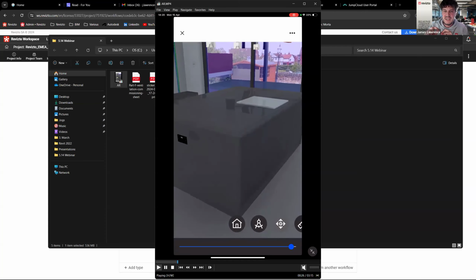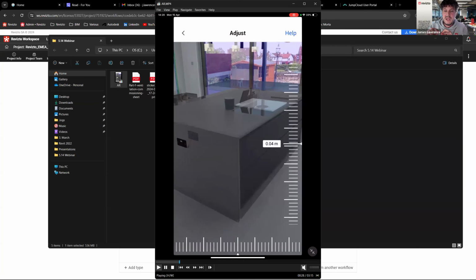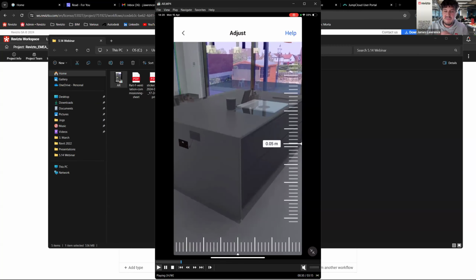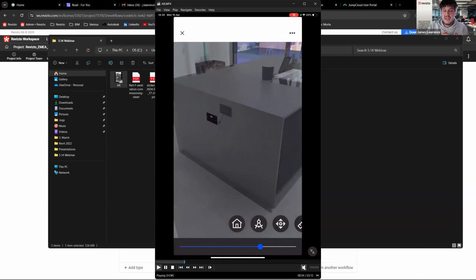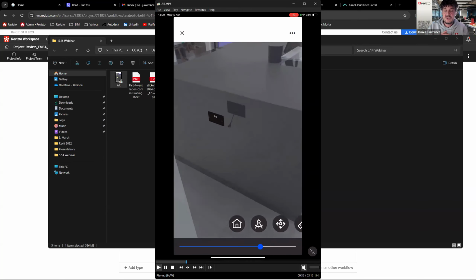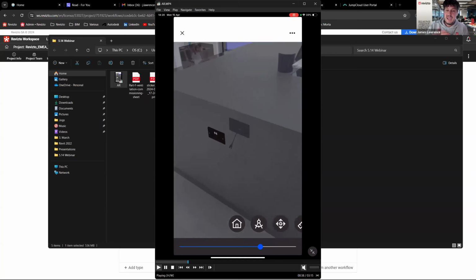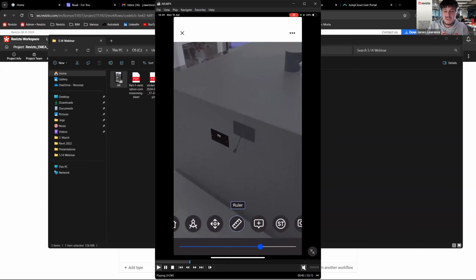That's probably due to the size of the kitchen island that's in there. But what I can do is change it after the fact. By changing it about 50 millimeters, it's now over the top of the kitchen island unit that we have. And here I can change the transparency. And straight away, I'm seeing discrepancies in what's actually been installed out on site to what is in the model.